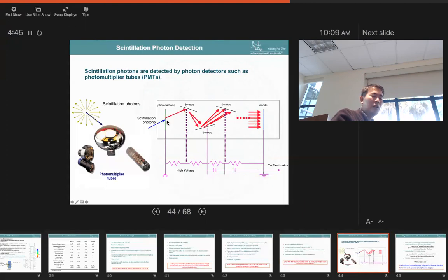Electrons come out of the photocathode and are amplified through steps of a dynode. This is called a dynode. An electric field is applied from the photocathode to the first dynode, and from the first one to the second dynode, because the voltage is applied all the way across, from photocathode to anode. So there's a cathode and an anode, those two main electrodes, but inside there are smaller electrodes called dynodes. Between the dynodes, with very high voltage applied, there is an electric field.